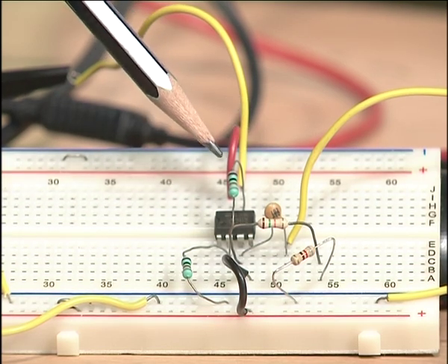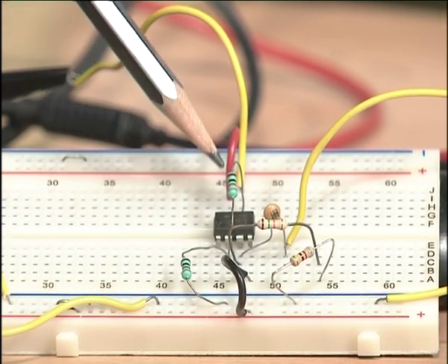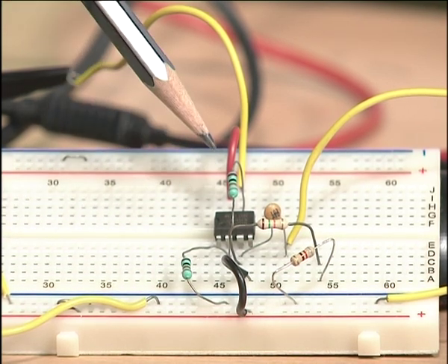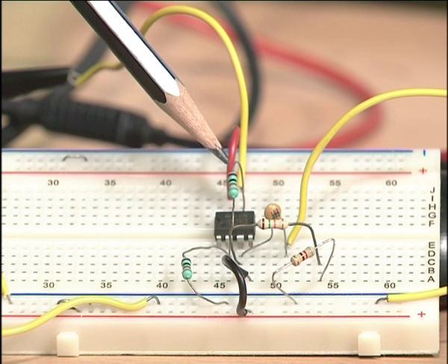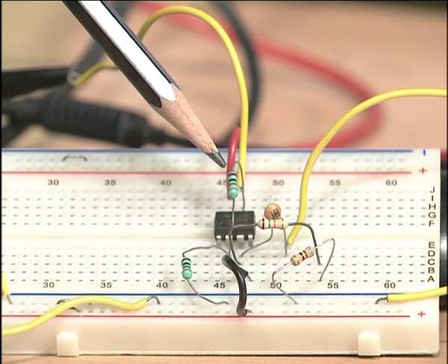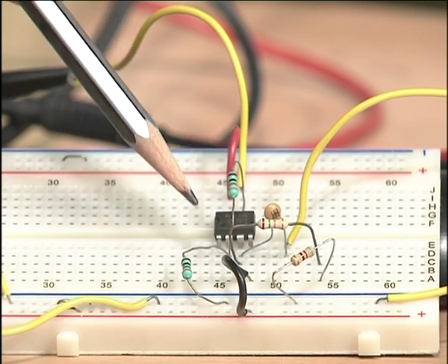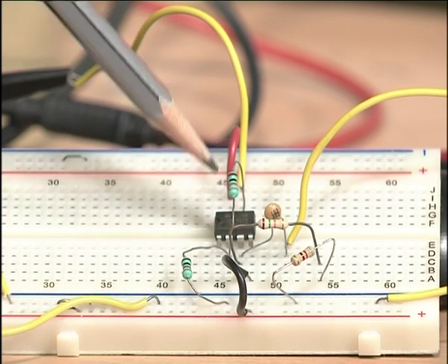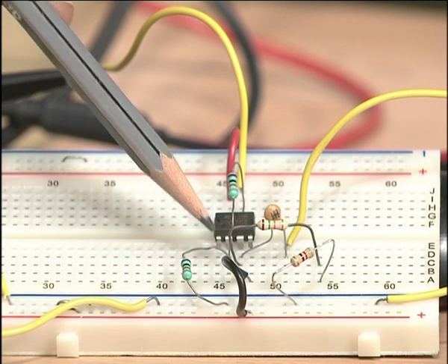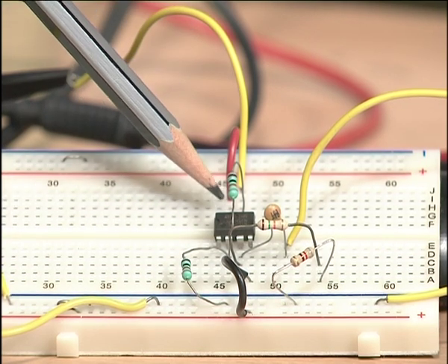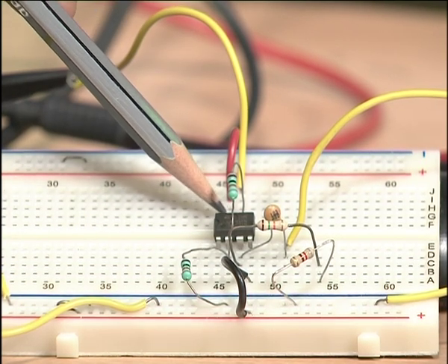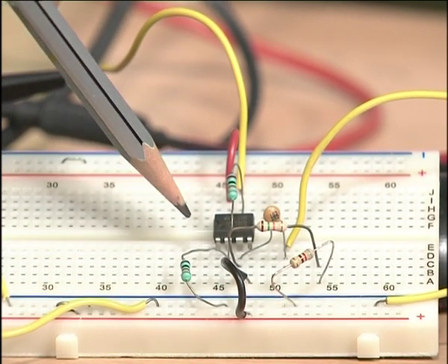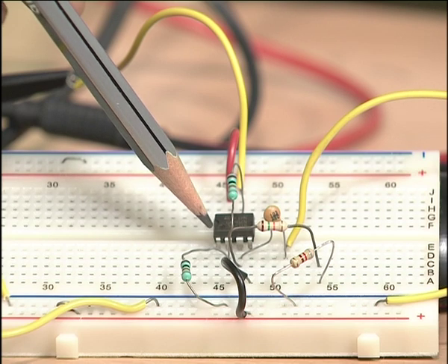Now, the circuit configuration here: one section is the passive filter section, and then what you can see are the two resistors here, RF and R1. This resistor here is the RF resistance, the feedback resistance, which is connected between the negative terminal and the output pin here. The negative terminal here is the second pin and the output pin here is the 6th pin for the 741, and the other resistance, which is R1 here, is connected from the negative terminal, which is the second pin.